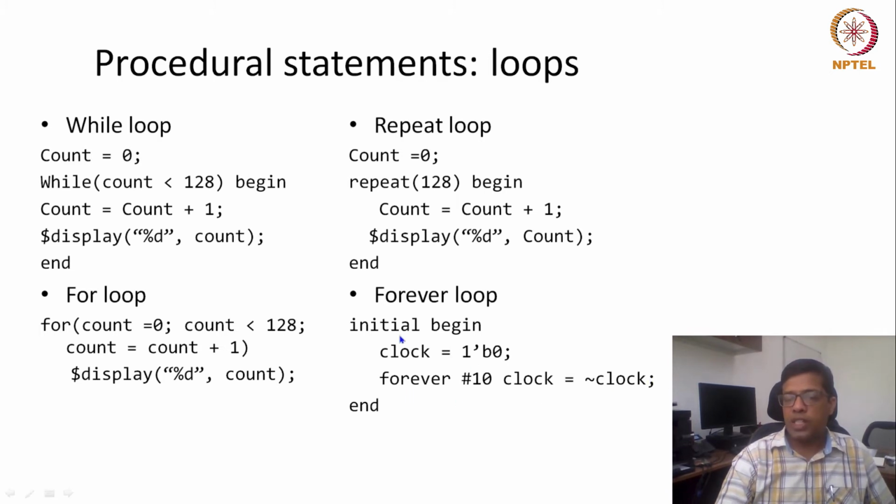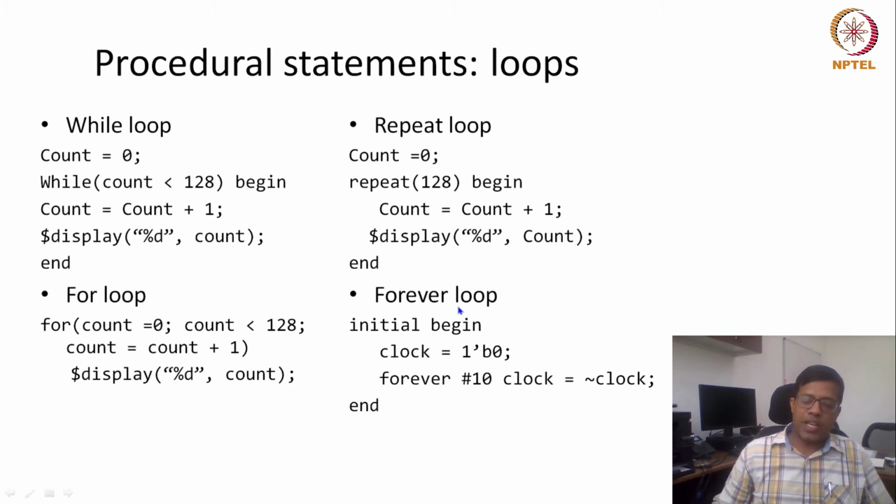Now, again, you will ask, does forever mean that it will keep on executing? Actually, yes. But what will stop it? If you are writing anywhere in your test bench or your design the condition on which you would like to do a $finish, for example after so many number of cycles, then the simulation can finish. Another option is to use a logical expression, and when this particular logical expression happens, you can assign a $finish. So that means your conditions.